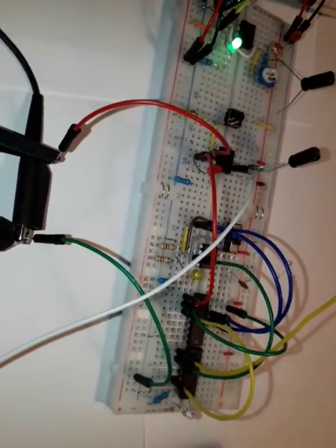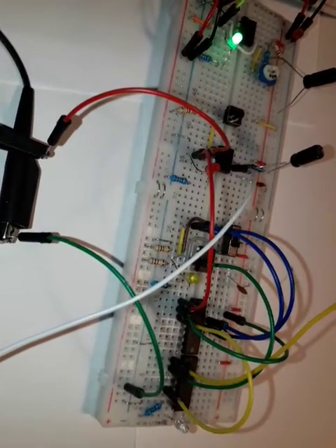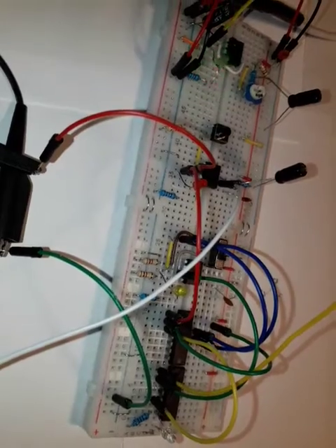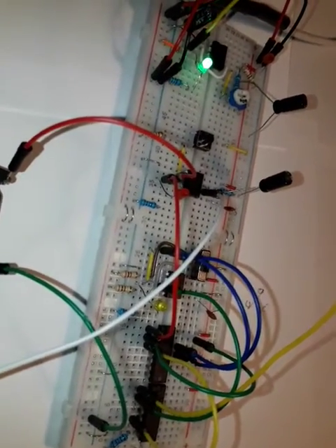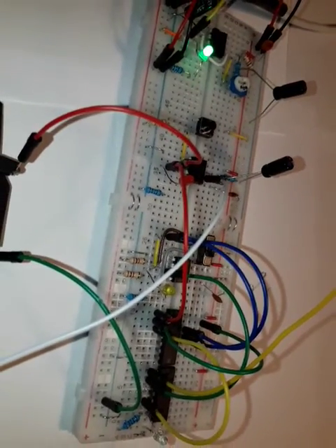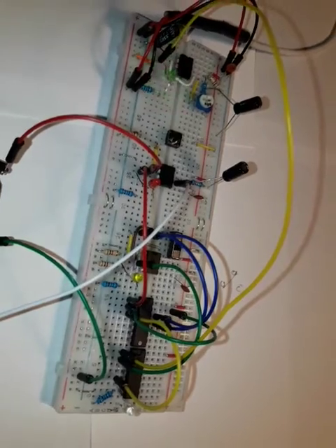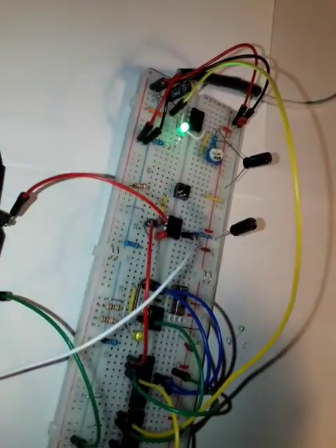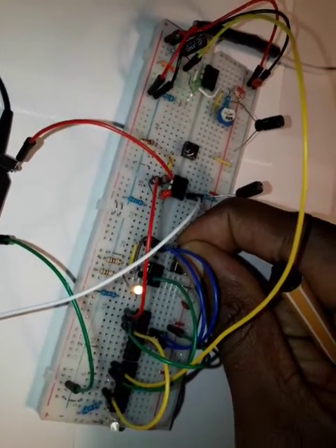But this I would use during the debugging mode, or when I want to debug a particular program and see if the computer is executing the task as expected. But then once I'm done, I can also switch the computer back to its normal operation mode by switching the clock system to the astable mode, and I just have to do that by toggling the switch back.